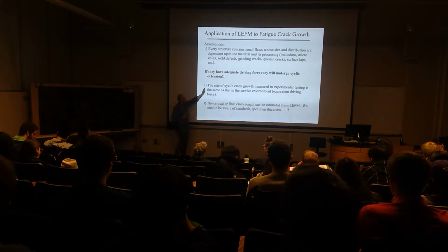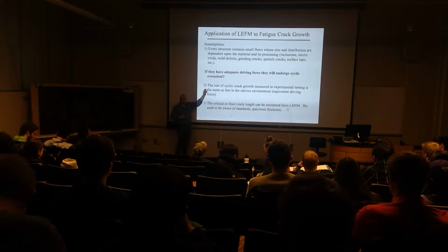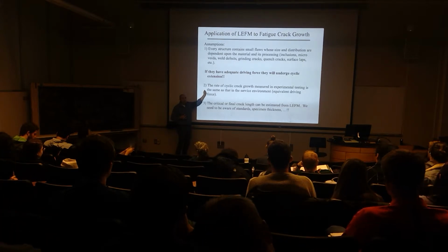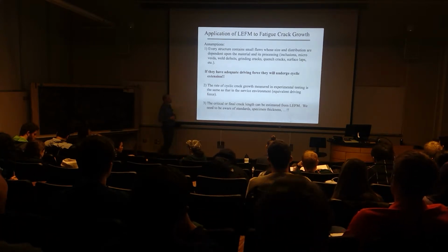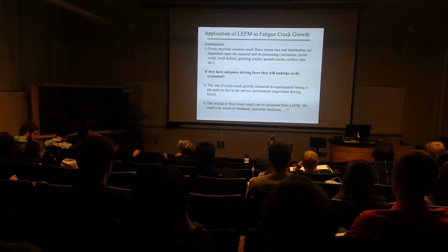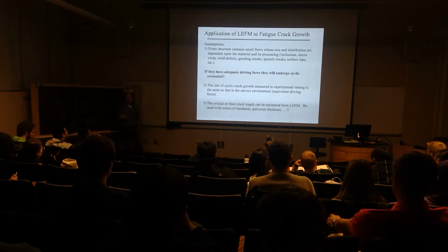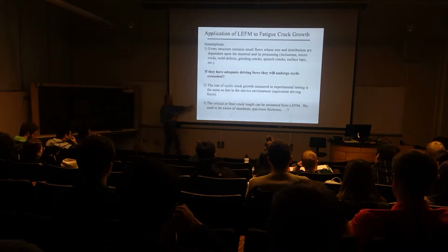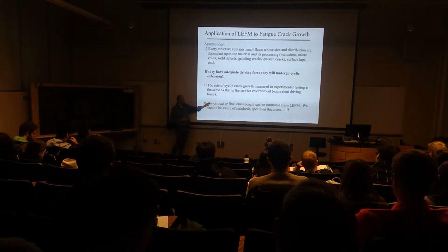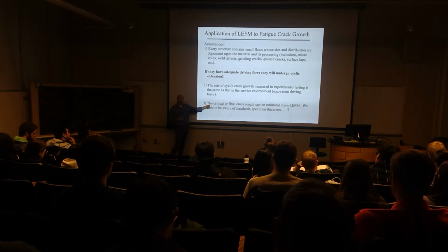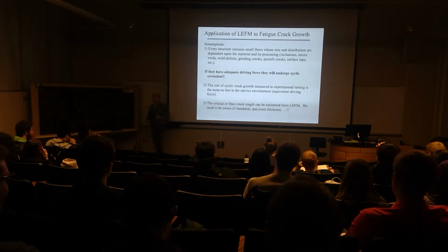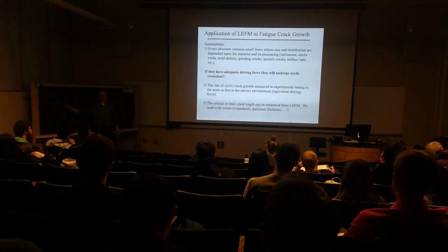And then what we want to do as well is we want to say that we can predict what that rate of cyclic loading will be from experiments that are conducted with that material in which we control the particular conditions. But we want to make sure that we're using equivalent magnitudes of the driving force, or the amount of the stress intensity that actually was contributing to fracture of that particular material and surface. And then eventually that crack will grow in a cyclic manner until it reaches the critical value where we can apply linear elastic fracture mechanics.